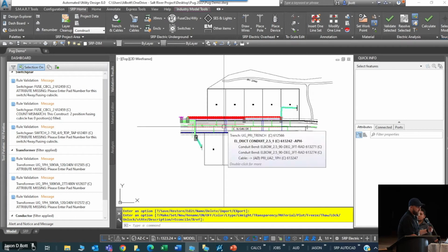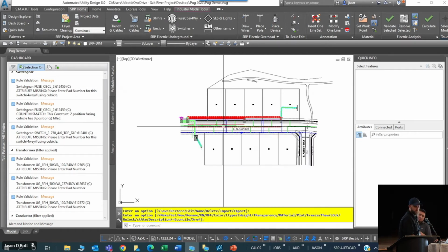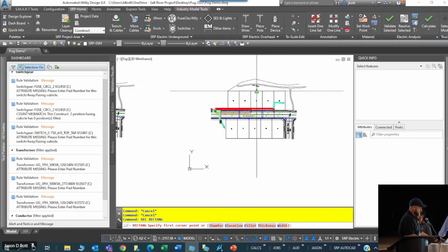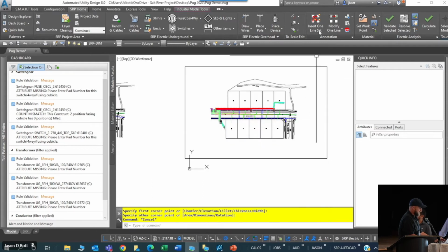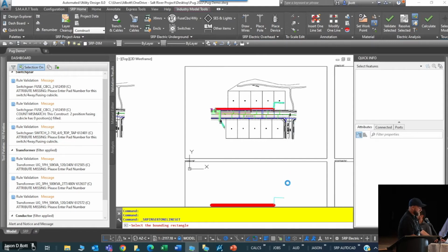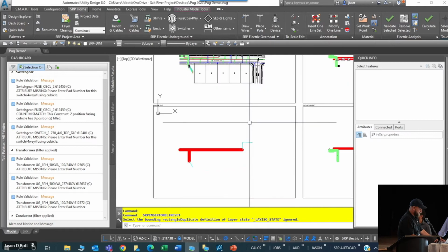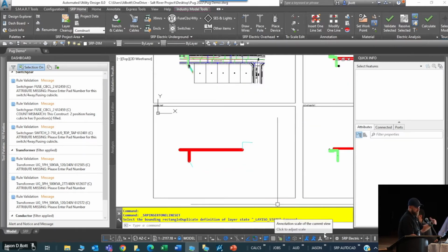But at that point, we do our 1 lines. So as Scott showed earlier, we represent a transformer 3 different ways, and we have 3 different layouts. So we leverage the 1-line tools. So if I just draw a box around this and I hit 1 line, after I've done my model, it literally will create my mainline schematic and conduit for me automatically, and it drives the rules. And then it's all annotative. So everything in my model is 1-to-1.